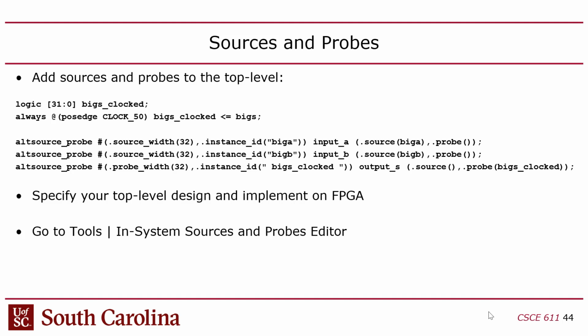This was something that was designed to help you debug your projects. I don't know if you'll ever need it, but you can actually put in your design ports that allow you to send data into those ports from Quartus. And you can also put other ones where you can read from. So these are like virtual I/O pins, basically, that you can access through JTAG. And they're called the sources and probes.